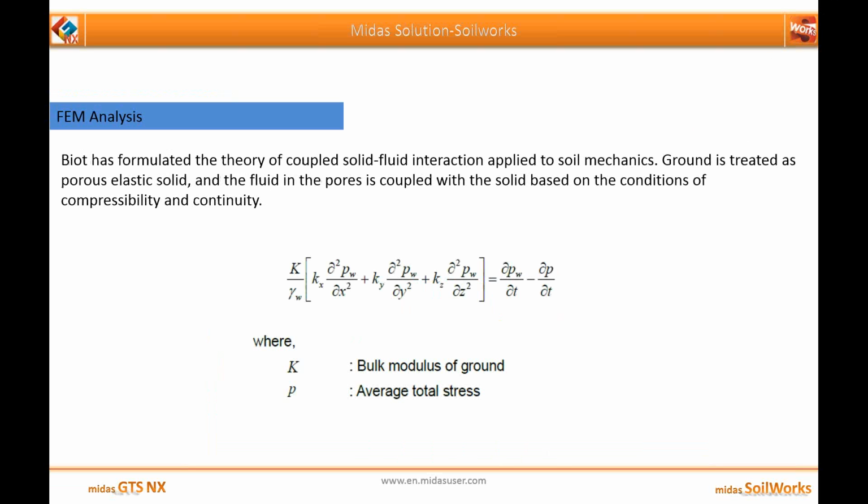Now till now we have dealt with 1D analysis. Finite element analysis is basically 2D, where if the settlement is happening, it will be occurring in 2D, not only in the vertical direction, but in both axes of the 2D interface. Now, in the finite element analysis, Biot has formulated the theory of coupled solid-fluid interaction applied to soil mechanics.